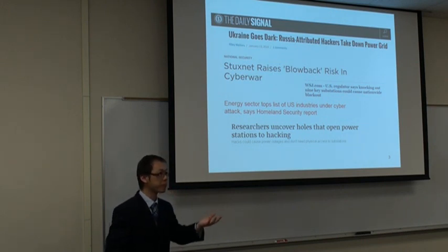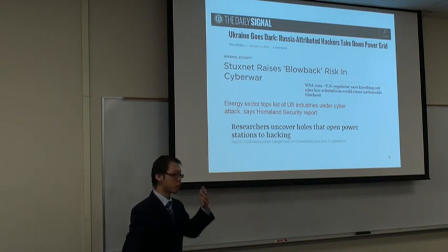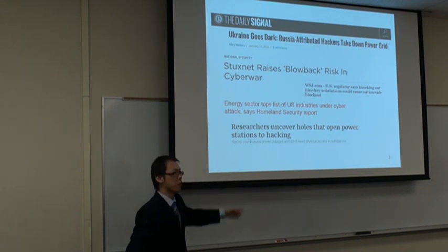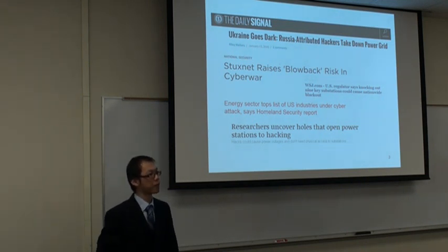Also it's about steady state. SCADA is 2 seconds to 6 seconds, and PMU is 120. Yeah, PMU is really, really challenging if I apply this approach directly with PMU measurement. And when you talk about renewables and smart grid, it's embedded with PMUs. Yeah, I agree with you.